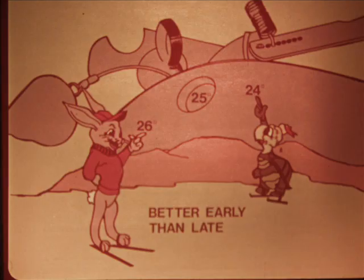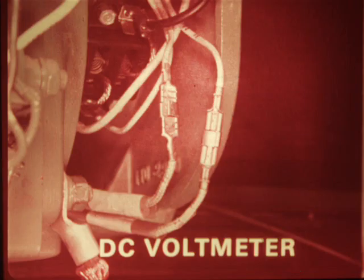Also, if you can't get dead on to 25 degrees before top dead center, it's better to go 26 degrees than 24. A retarded spark makes the engine run too hot. Now, if the engine is tuned properly, it should be able to pull a load without a big drop in output. So if engine RPM doesn't drop much, but voltage output does, there's a good possibility that the compounding reactor is bad. To test the reactor, lift the plastic flap and connect a DC voltmeter to the field leads.